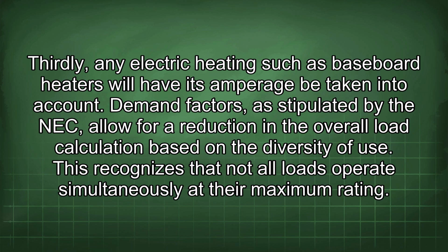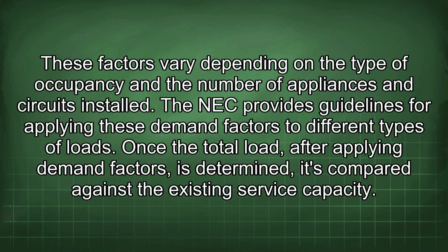Demand factors, as stipulated by the NEC, allow for a reduction in the overall load calculation based on the diversity of use. This recognizes that not all loads operate simultaneously at their maximum rating. These factors vary depending on the type of occupancy and the number of appliances and circuits installed. The NEC provides guidelines for applying these demand factors to different types of loads.